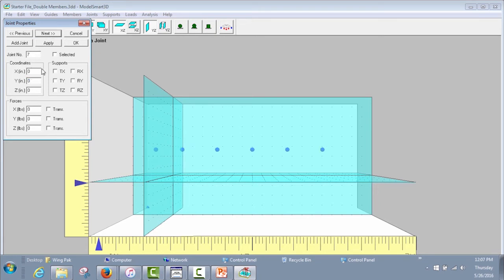So this is the reason why we basically raise our bridge 1 inch above in the Z direction above the origin. If we accidentally create an extra joint or duplicate joint, most likely that joint is going to be at 0, 0, 0. By raising our bridge up by 1 inch, it makes that duplicate or extra joint easier to spot and for us to go back and delete.